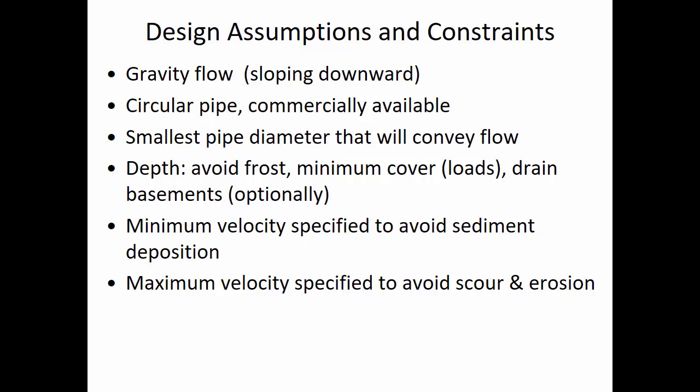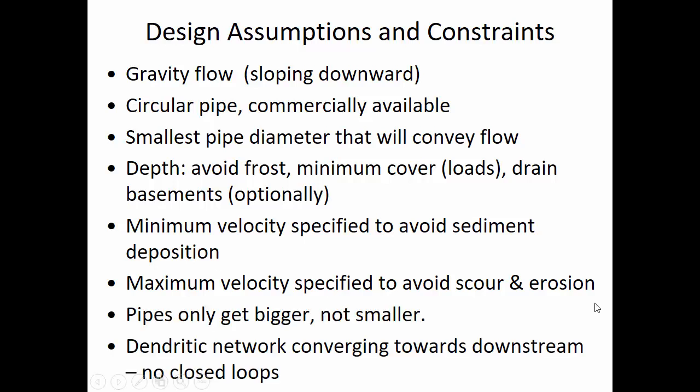So a place like Morgantown, where it's really hilly, they would maybe look at certain parts of the stormwater network and choose a pipe that's more resistant to scour. So maybe a plastic pipe instead of a concrete pipe in some of those really high slope areas to avoid scour of the pipe.